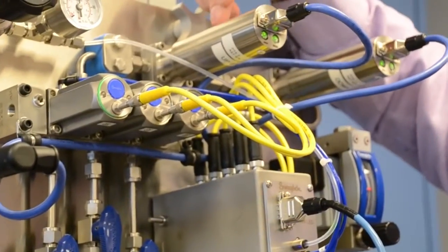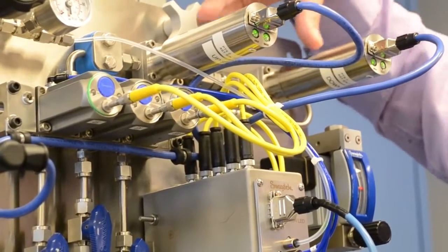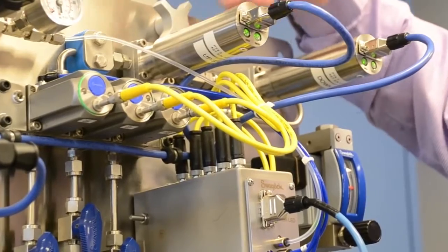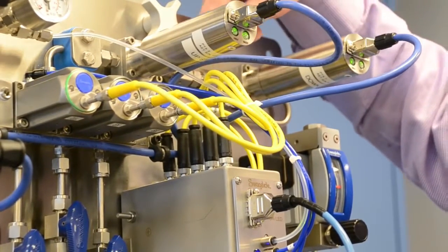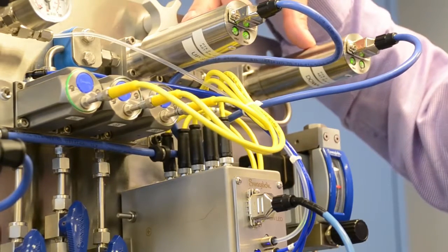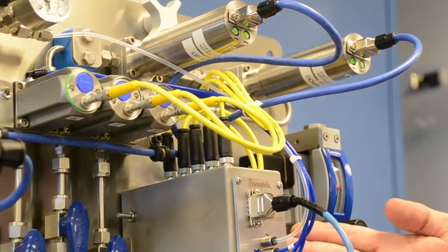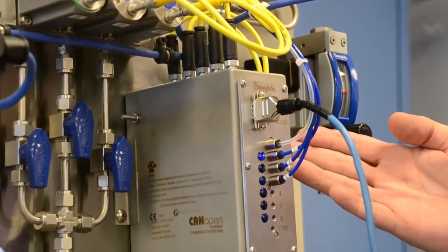These products, as their name implies, measure both pressure and temperature. We have two of them in this system because by using two PTXs with the flow restriction in between, differential pressure can be measured, allowing the ICM to turn that differential pressure into an actual flow measurement.